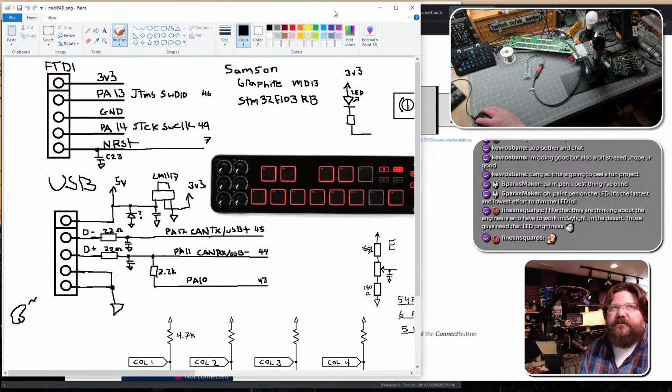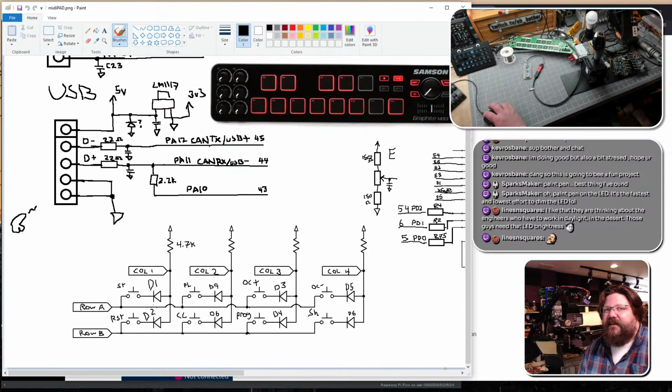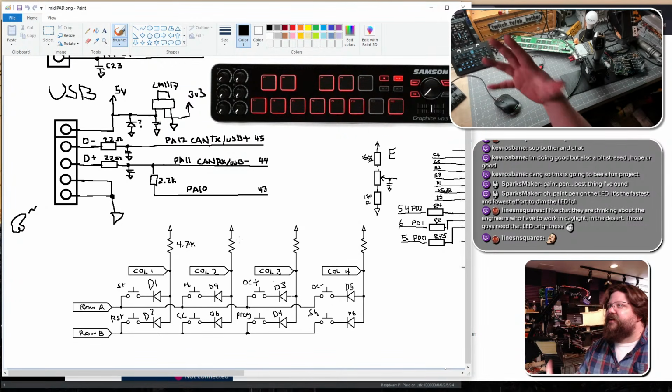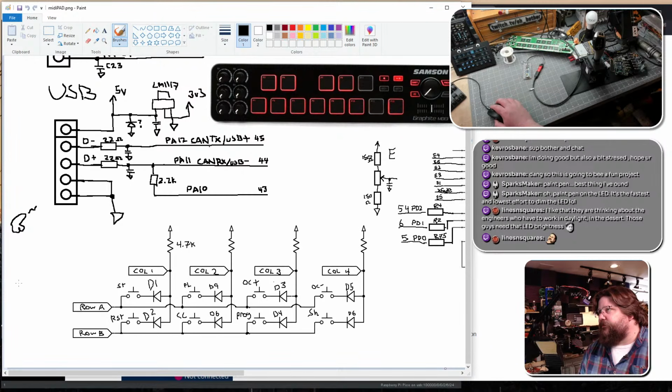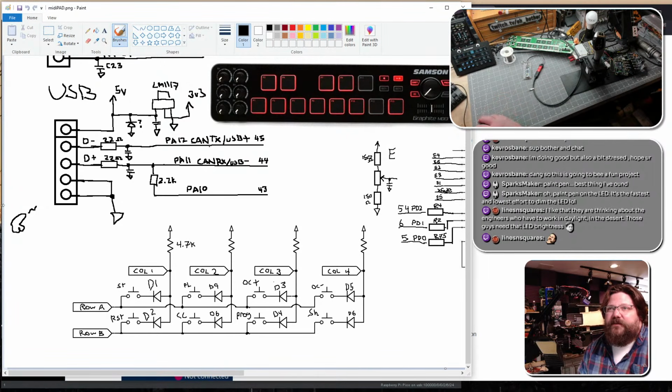Schematics are a communication from engineer to engineer, or from engineer to themselves, and the symbols that you use need to be consistent within themselves. Generally, when reading a schematic, you're reading it like a normal document, left to right, top to bottom, although schematics can tend to cascade down and out, and you try to structure things that communicate different known arrangements of device symbols. So if you're using op amps, you have the thing that goes up and around to tell you that it's doing a feedback loop kind of thing.